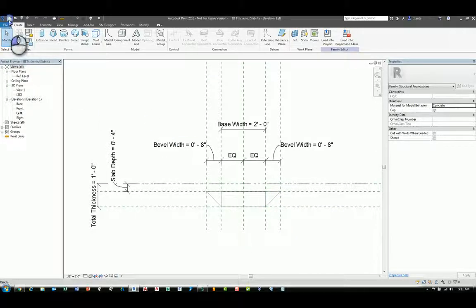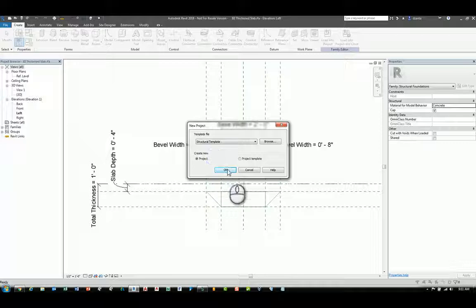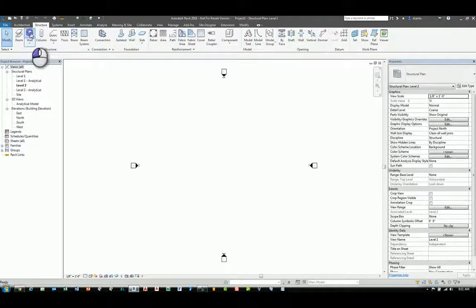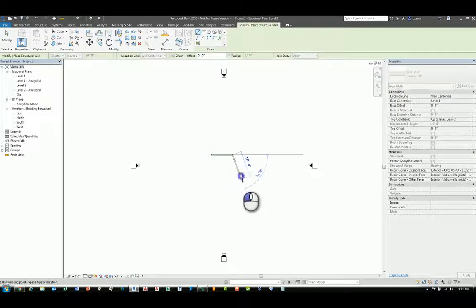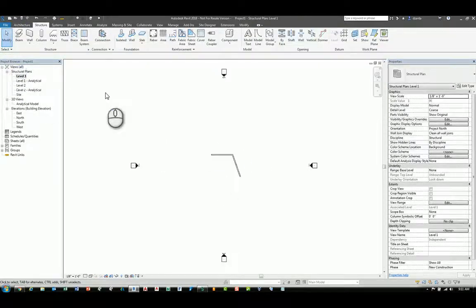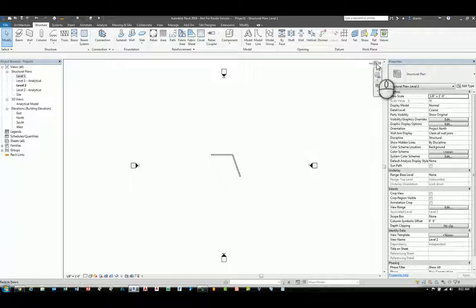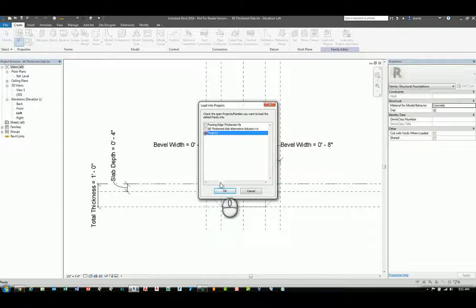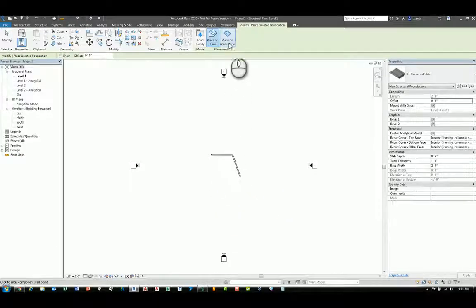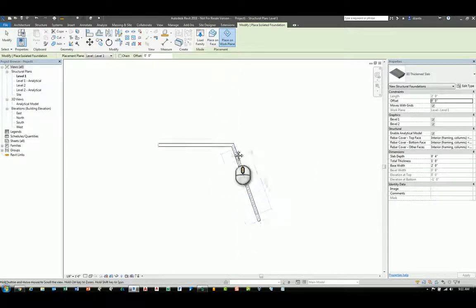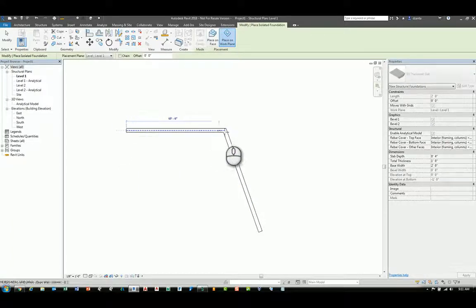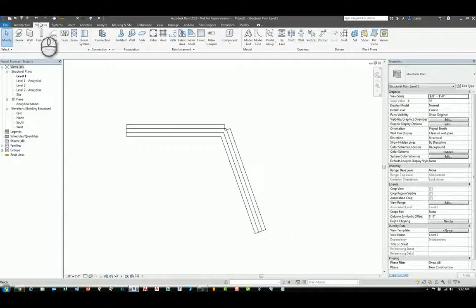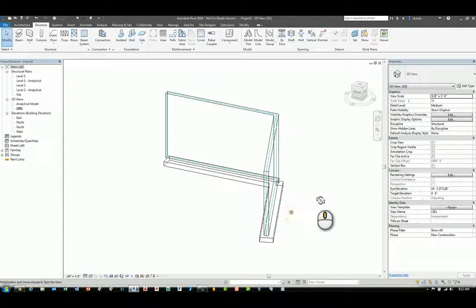If we look at it in the context of a project and start a new structural template project, we'll head over to the Structure tab, create some structural walls, head over to Level 1, swap back to the profile that he's working with. We can load it into the project, and then his function and use is placing it on the work plane where he draws it on the center line of the wall. When he does this, it places that particular profile and usage here.